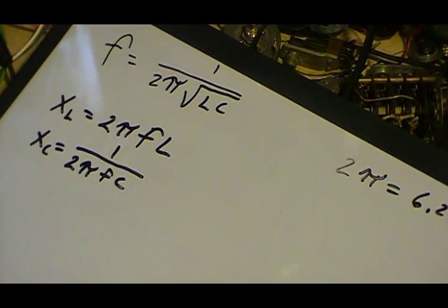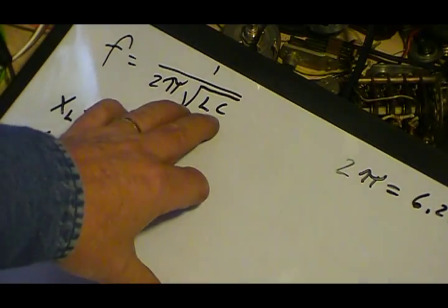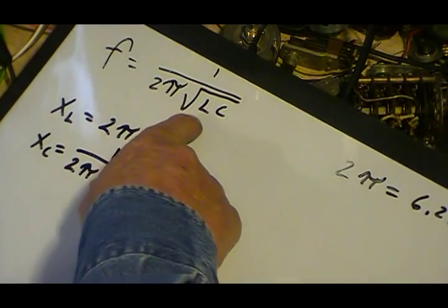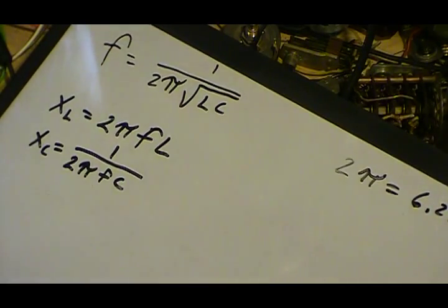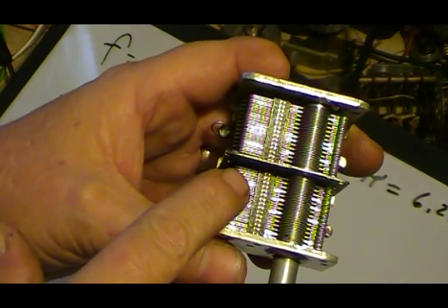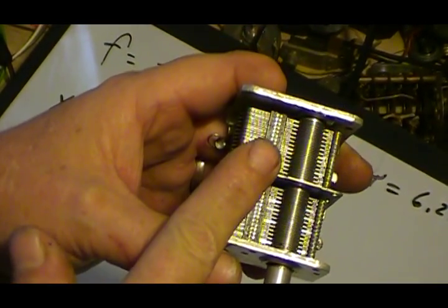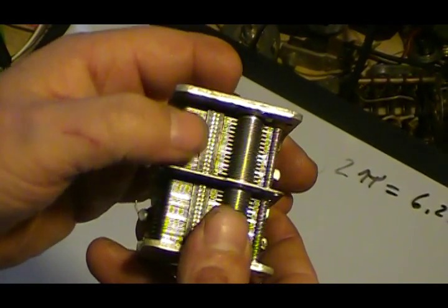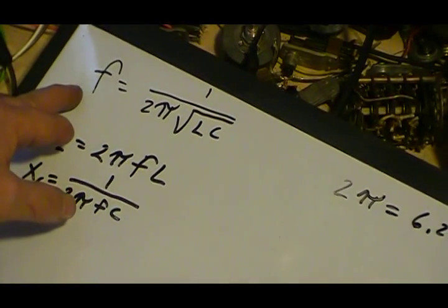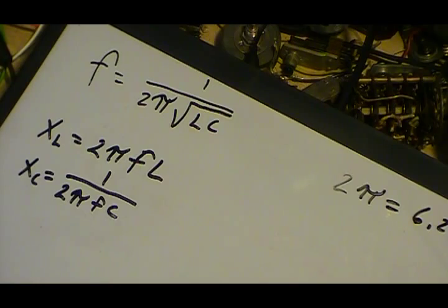Now, yes, there are some radios that are inductive tuned, and in that case the capacitance is fixed and the inductor changes. But if you're working with this formula and you have that indirect proportionality there, the inductor is fixed and the capacitor is what's turning. When the variable capacitor, your tuning capacitor, is fully closed, it's got maximum capacitance. So at this point, when it's completely closed, it has maximum capacitance, the frequency is the lowest for the radio.